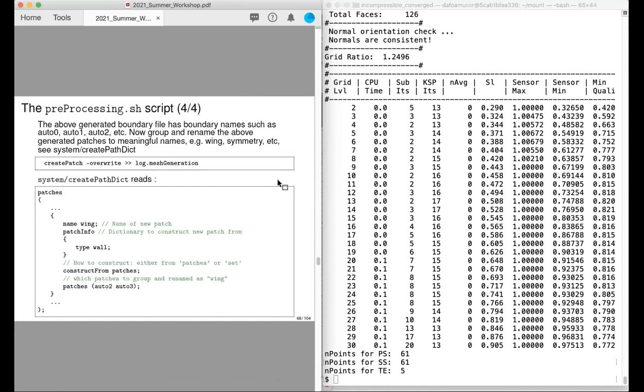I see your question about a general mesh density box. Well, right now, PyHyp does not support that. At least DAFoam does not support that. If you want some refined mesh to capture the wake, you have to use an unstructured mesh. The short answer is no. PyHyp does not support that, at least for DAFoam. Does that answer your question?